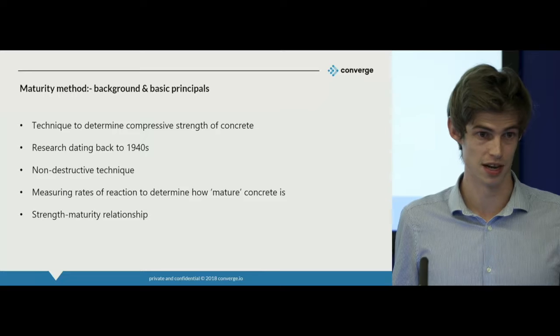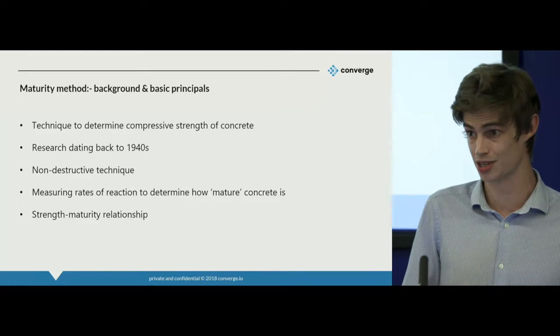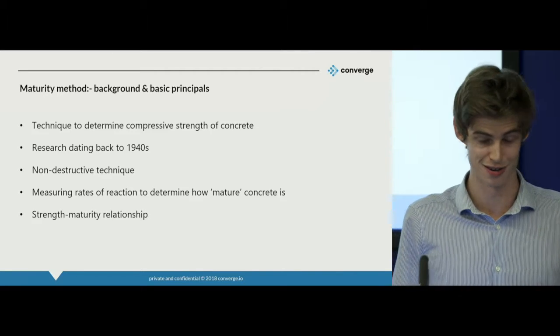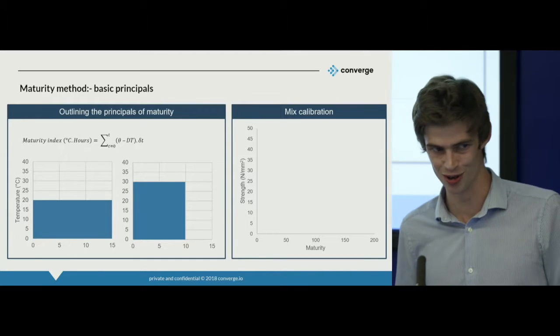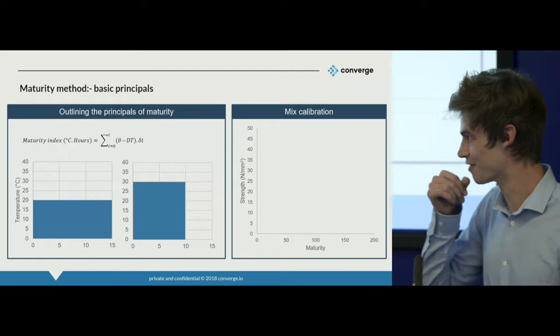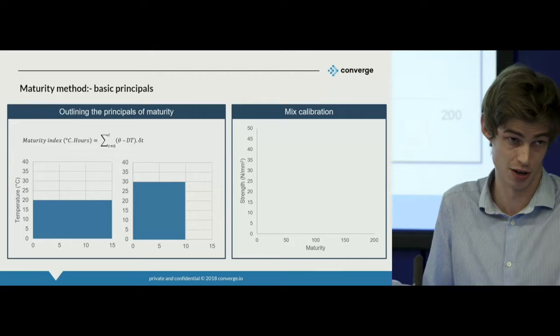It's a member of a class of techniques known as non-destructive techniques. Traditionally with concrete, you have to destroy the sample to know what strength it is. But with these techniques, you needn't do that. You can determine the strength in other ways. I'm going to paint a very quick example for you here and then move on to some slightly more fun stuff. We see here, in effect, that they would integrate underneath the temperature profile of the concrete itself.